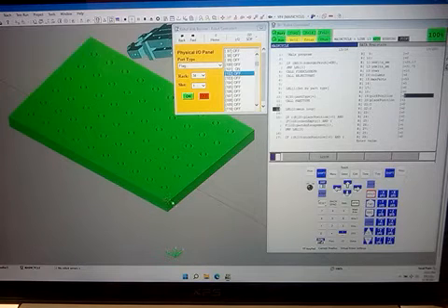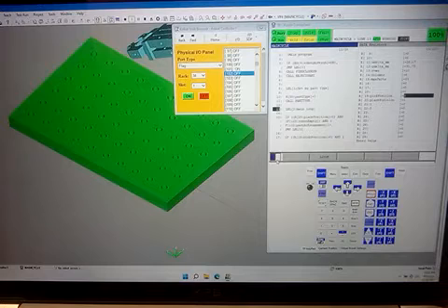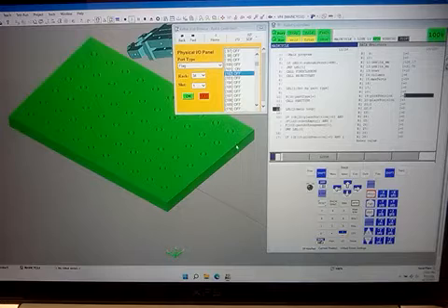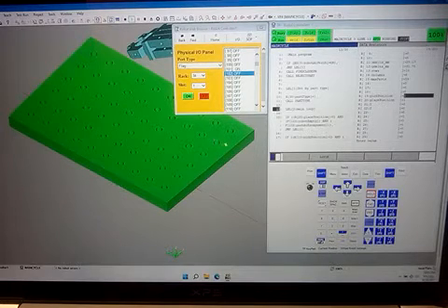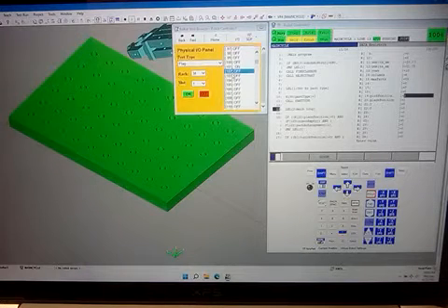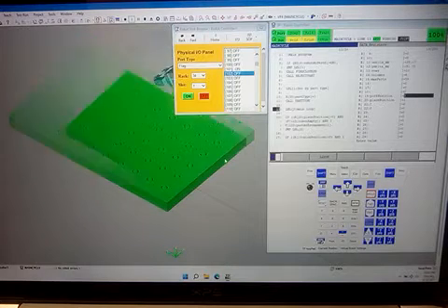We're going to have some sensors attached to the heat plate to instruct the PLC on what part type is going to be running. So the PLC is going to be the driver of what part type is being selected, and the robot is just going to be adapted to it. Right now I have some flag bits to signal the robot that there is a part present at the station, and so on.